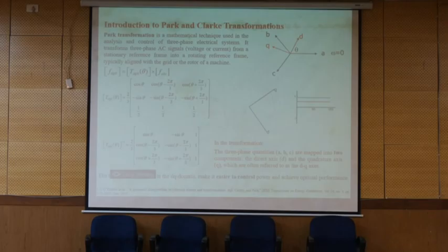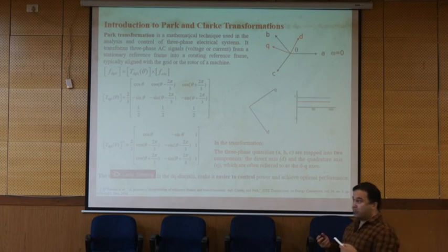It means that reactive power is coming from the converter, active power is coming from the grid. So the power factor is equal to P over the square root of P squared plus Q squared. So when Q is 0 on the grid side, the power factor will be equal to 1. Okay? So all in all, you can tune your converter, and based on the demand, you can control it and get the maximum benefit.